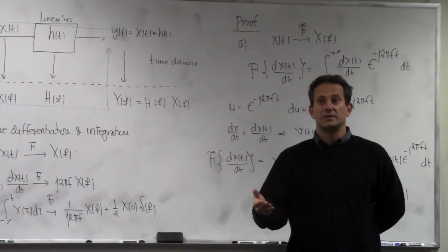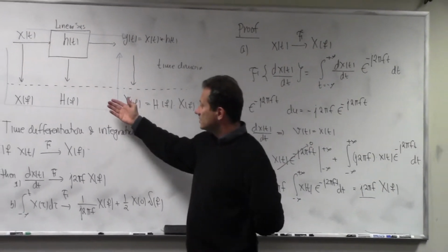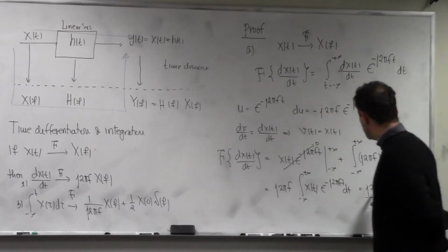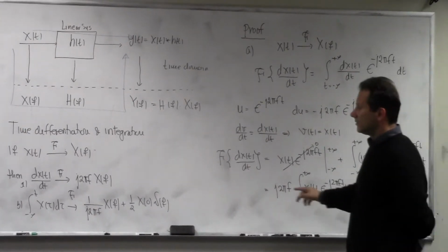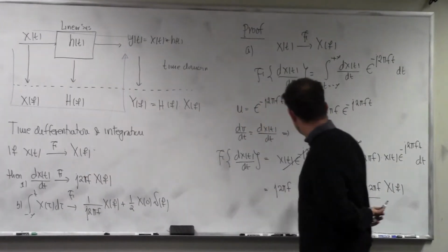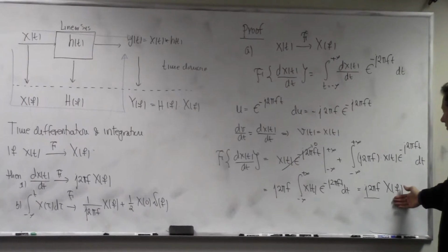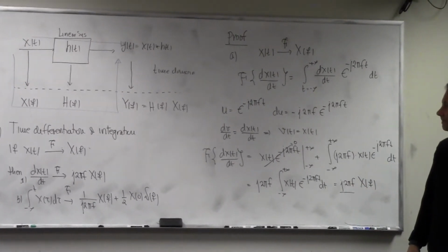It's a linear filter, right? It's a filter that has a frequency response given as j 2 pi f. And this whole differentiation in the time domain is essentially equivalent to modifying the frequency content of your signal by multiplying everything with j 2 pi f.